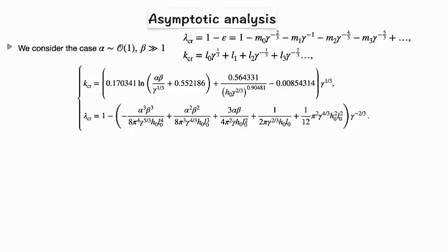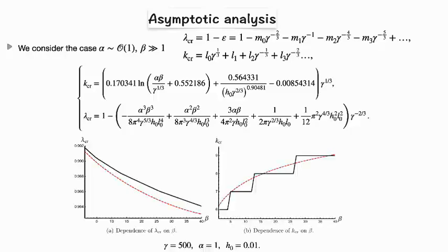You can see that the modulus ratio and alpha beta both occur in the leading order, and it affects the critical wave number through the log term. It means that it makes a very big difference. You can see that when you increase beta, there is a very big difference. So in the previous case, the gradient modulus doesn't make sense actually. The structure cannot see the gradient modulus, but in this case, it makes a great difference. So you need to consider the gradient effect.